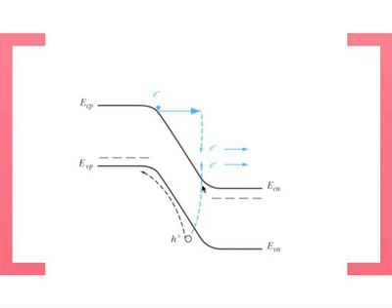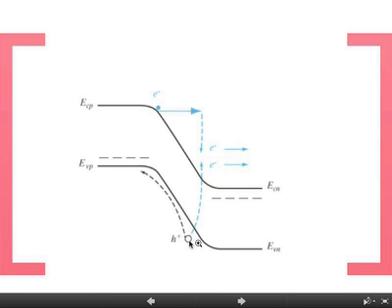Again, from the band diagram perspective, the bands look exactly the same as the case of the Zener, except that now you see that the transition region is much wider. So the tunneling probability here is very small, and you have low tunnel current. But the electron that gets accelerated through the field has so much kinetic energy that it can hit an electron which is in the valence band, in the bond, and kick it up to the conduction band.